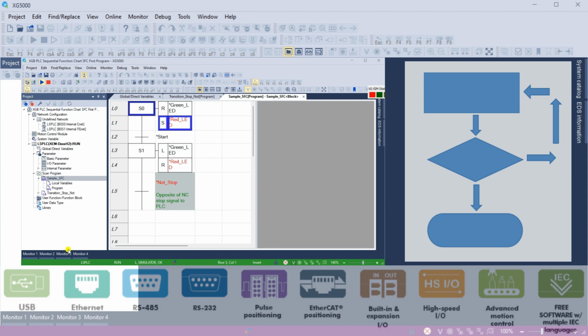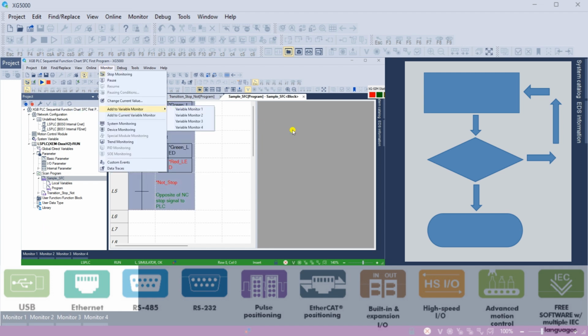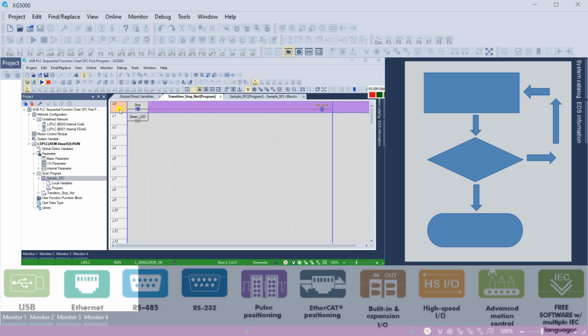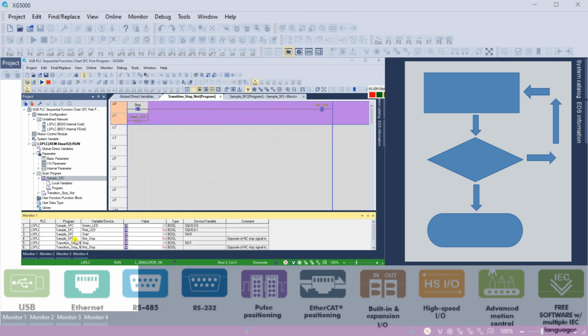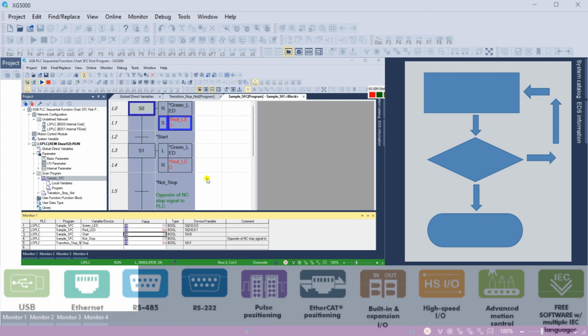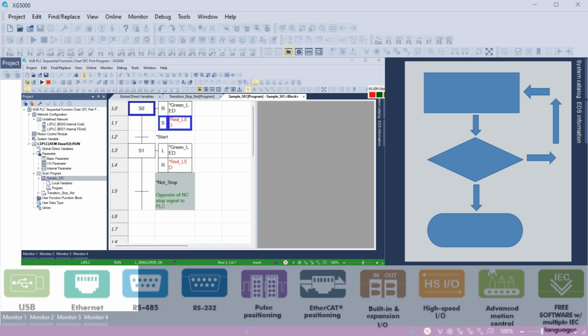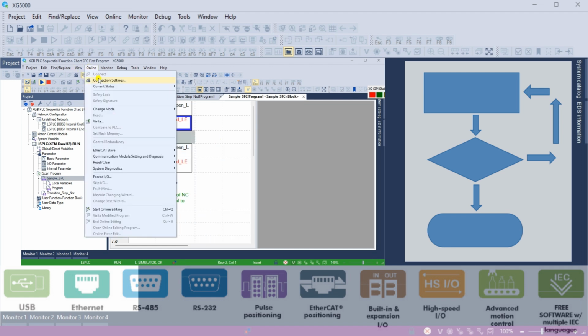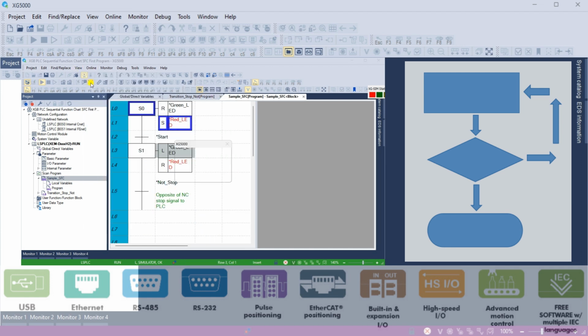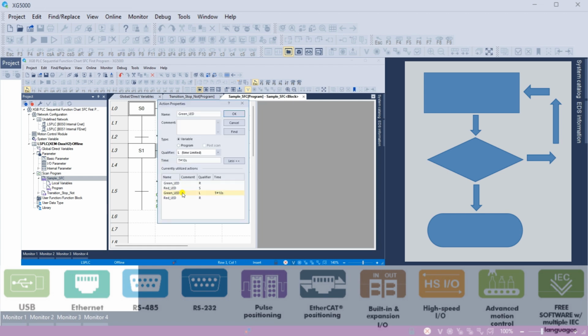In this session, we will be leveraging the PLC Simulator within the XG5000 programming software to explore Sequential Function Charts (SFC). The graphical step and transition views significantly ease the troubleshooting process for SFC programs. Although SFC programming is frequently underappreciated, it stands out as an effective method for program development. This approach allows you to translate your program's sequence of operations directly into the PLC.